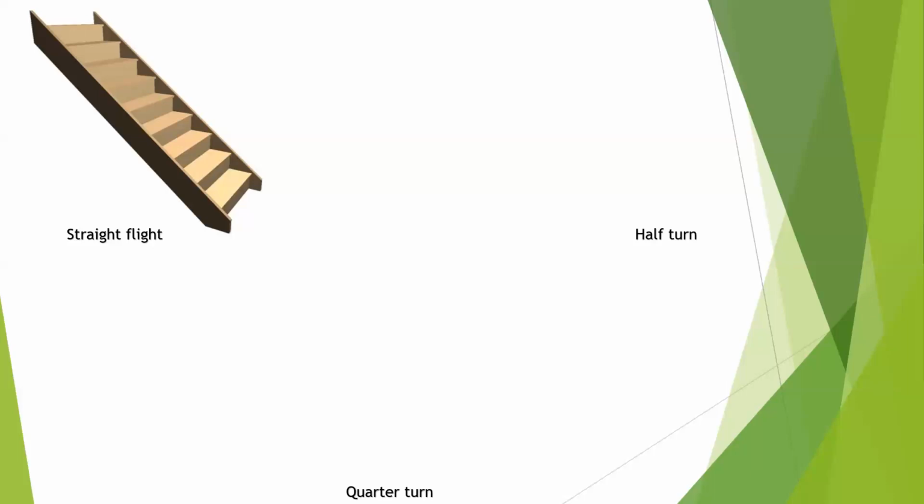Your concrete grade must be what it is. Then every other thing must be according to the requirements or factors you have used in your design. Talk about your strength of steel and then your concrete strength also. Then your spacing must be thoroughly adhered to. So it's something that requires thorough supervision, as simple as a straight flight could be, because a lot of it has failed. And if it is simple to do, it shouldn't be failing as it is failing in the construction world today.